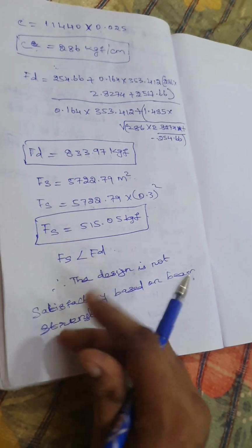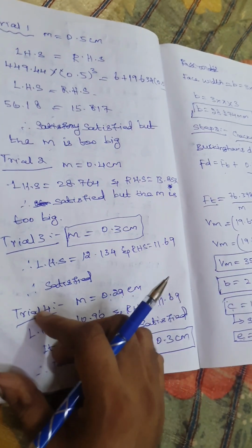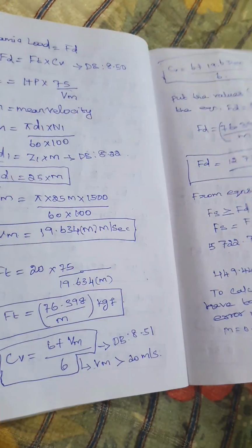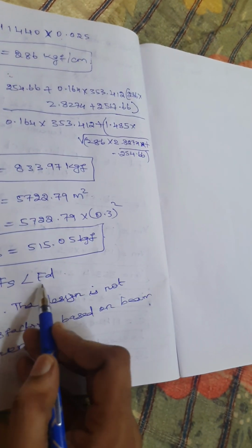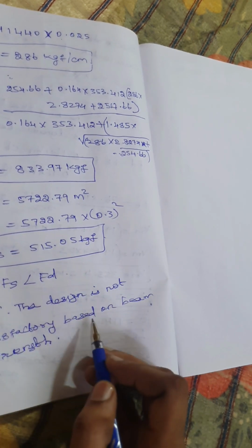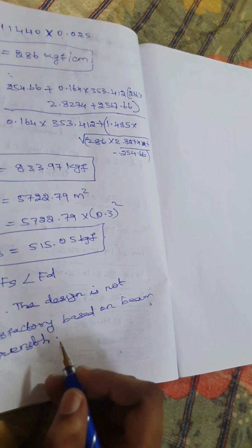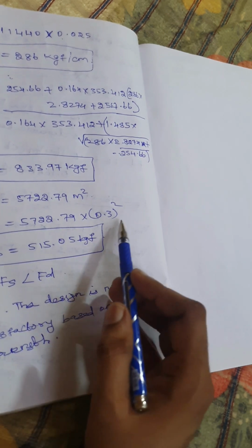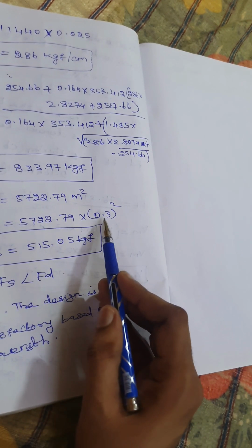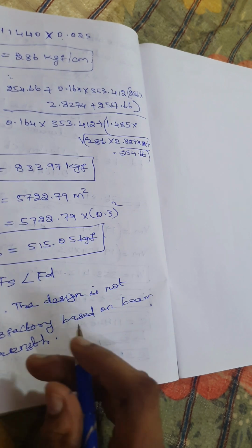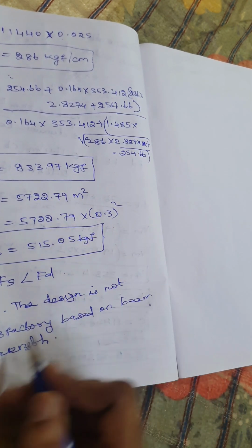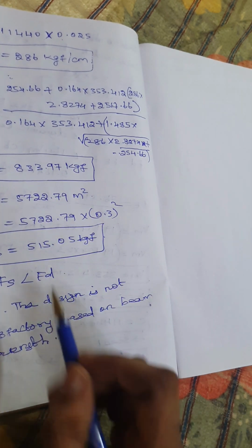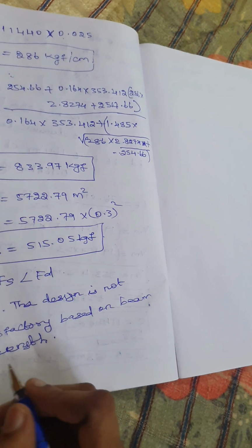We are, as we already said, f of s should be greater than or equal to f of d. Here the f of s value is smaller than f of d, therefore the design is not satisfactory based on beam strength. Therefore we should go for the higher value of m here. So we have considered three values like 0.3, 0.4, 0.5. Here 0.3 is not satisfied for f of s, so we have to consider